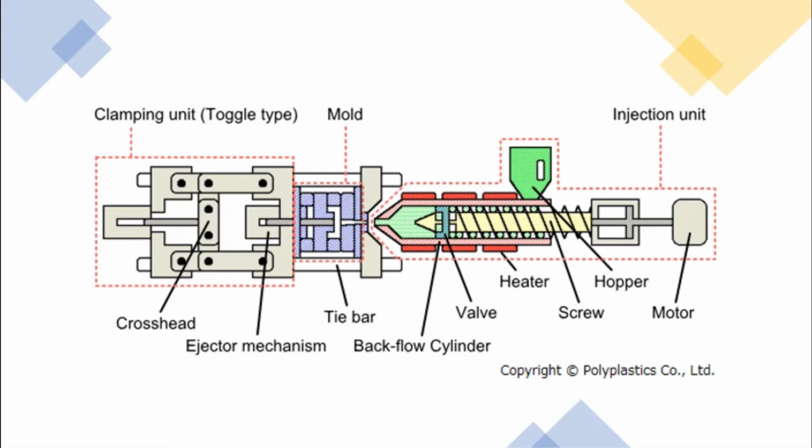As the required amount of molten plastic is accumulated, the injection process is started. On the other side of the barrel, a mold cavity is attached. The mold is located inside the mold cavity and a movable pattern is used in the whole manufacturing process. While molten plastic is flowing in a mold, the machine controls the moving speed of the screw, or the injection speed. On the other hand, it controls the pressure after molten plastic fills out the cavities.